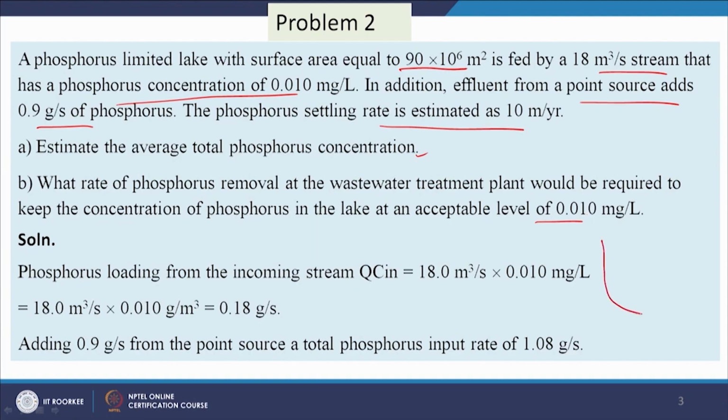If we have a lake, we have one stream here going in and it is going out also, and another point source somewhere here giving phosphorus. Now, at steady state, what will be happening? The sum of phosphorus in the input stream minus disappearance due to reactions or settling is equal to the phosphorus going out.